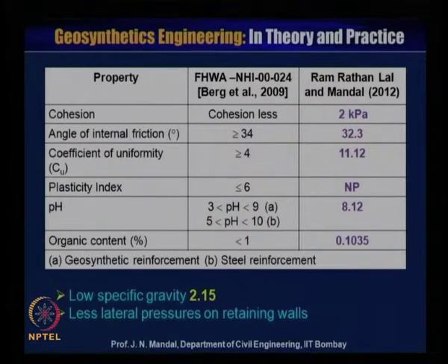So, here is the result obtained by Ratan Lal Mandal 2012. The cohesion value you can see is less than 2 kilopascal, the angle of internal friction is 32.3 degrees, the coefficient of uniformity is 11.12, the plasticity index is non-plastic, the pH value is 8.12 and the organic content is 0.1035.